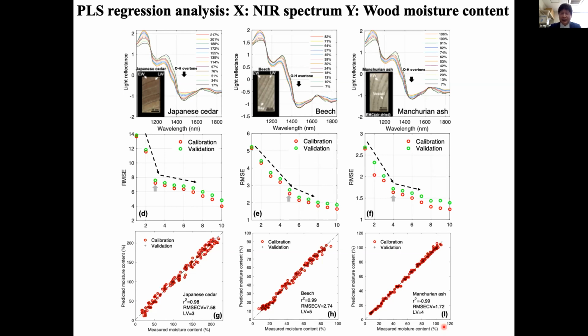Yes, because it is air drying. Natural drying is eco-friendly. Also, the damage to the wood materials is less than with artificial heat drying. The problem is that the wood industry needs drying efficiency, so artificial heat drying is increasing year by year. They use heat to dry the wood faster. But if you dry the moisture faster, the shape of the wood itself will change. So we need monitoring technology to check the water content changing characteristics. We try to balance efficiency with the high quality of the materials.